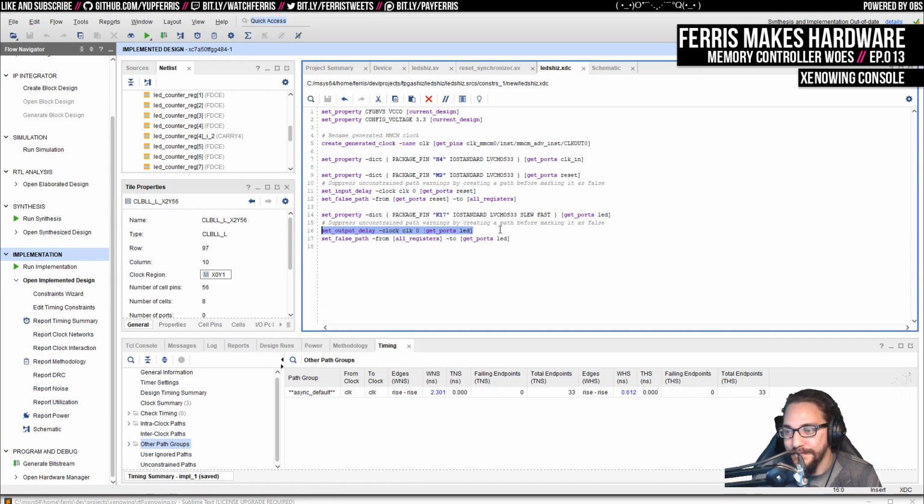But so it's really frustrating when my design would sometimes not work, and I'm quite convinced that was the reason. I don't think it's logic errors because I verified the logic in the Verilator sim, which of course doesn't actually simulate any timing related stuff anyway, so it's only simulating the logic. And then there's of course ways to also write Verilog so that you generate primitives like latches that have timing problems sort of inherently, but that's actually fairly easy to avoid. I don't think I've made any of those mistakes either, but I might have. But I don't think so. I think it was always timing when this was actually an issue.